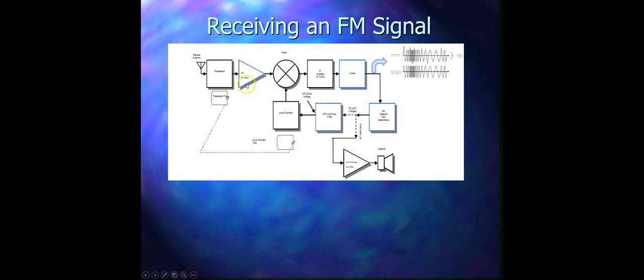Next comes the radio frequency amplifier. This radio frequency amplifier provides two important purposes. First, it is used for amplification. The signals from the antenna are very tiny. When you receive the signal over here, the magnitude of that signal will be very small, a few millivolts or a few microvolts. This small signal is mixed with the local oscillator here. When it is mixed with the local oscillator, it can be easily lost in the noise from the mixer. The mixer adds considerable inherent noise to the signal that passes through it.